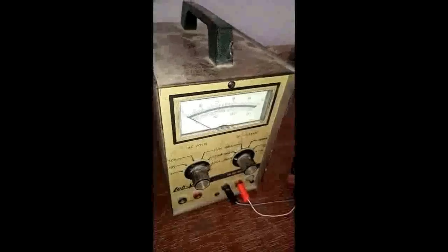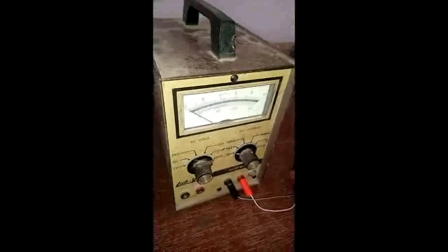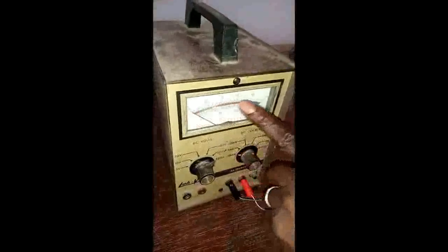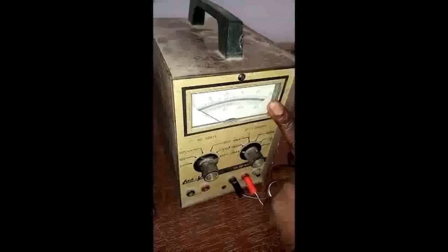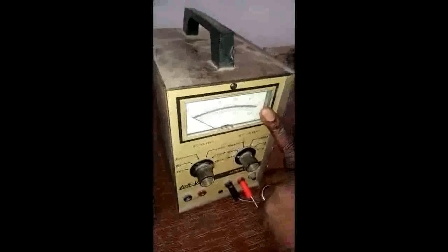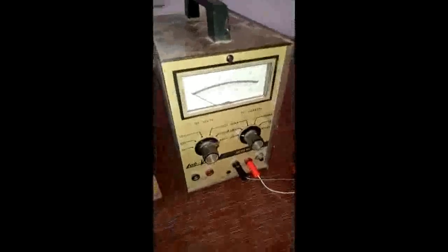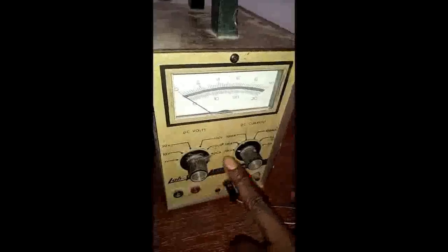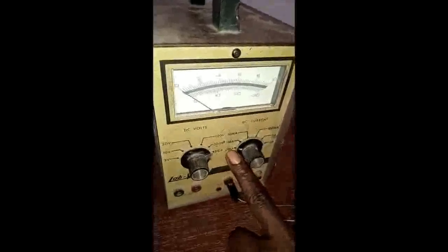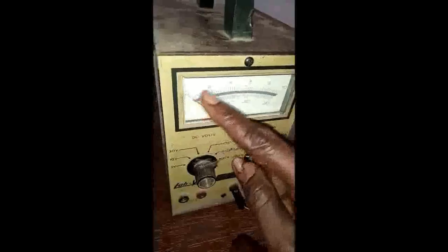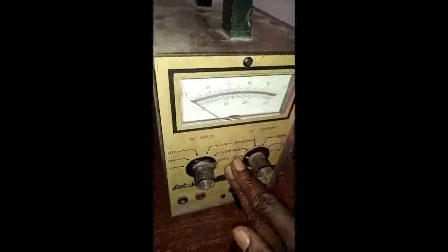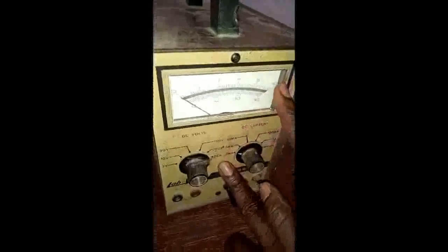What must first come to the mind of any student is to use the upper scale, and you divide that one by 100. If you divide 10 by 100, what will it give you? That is 0.1. That is to say, the full scale deflection, FSD, is now 1. When you set this on 0.1 milliamp, it's now 0.1. But what you need to do is just to make sure that whatever reading you get, anytime you select this range, you just divide by 100.